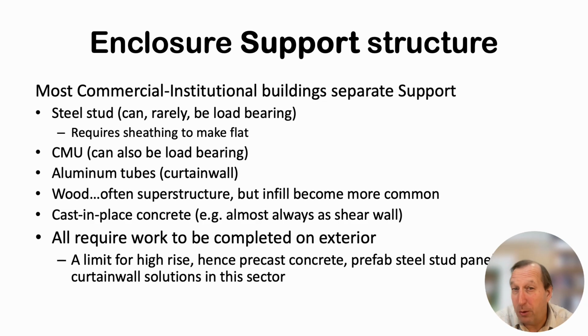Wood, as I mentioned, could be both its own infill support structure, or it could be part of the superstructure. It's your job to identify which it is. Cast in place concrete is almost always part of the superstructure, but it can also act as the support structure at the same time. It rarely acts only as support. And all of these systems require assembly from the outside and the inside. You build the superstructure, and then as a support structure, you have to put this together. And that limits their utility when it comes to high-rise buildings where we don't have easy access from the outside.